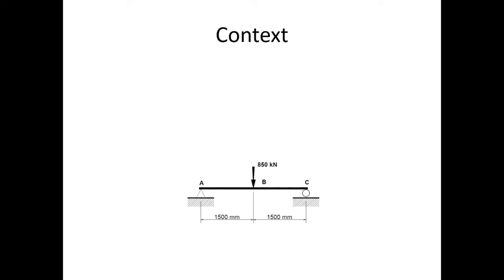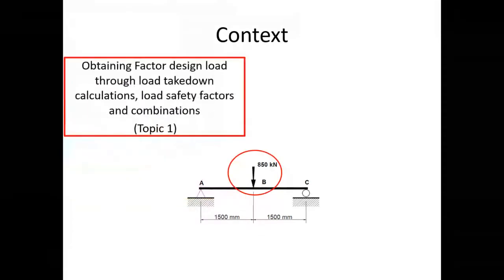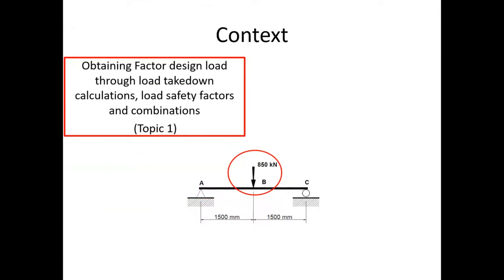As I said, we previously concentrated on beam design, on individual members, a member in compression, a member in tension. What we now need to do is take the whole system together. We've been looking at the applied loads on a structure. We apply load factors and combinations to make sure that the structure we design is going to be safe. The load goes down through a member, in this case a beam, or in another case an axially loaded member, like a column or a member of a truss in tension or compression. And that has to go down into a support and safely into the ground.